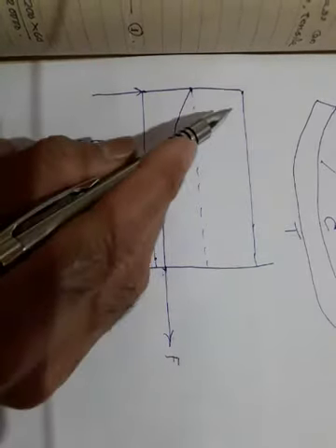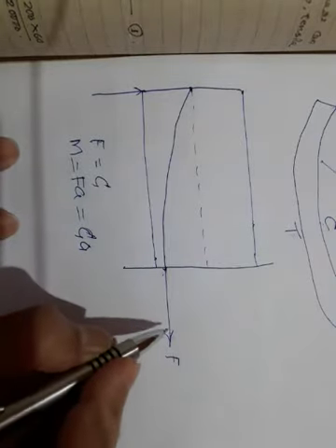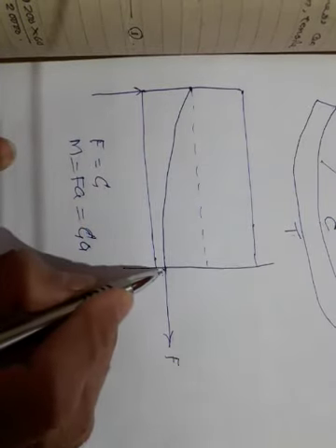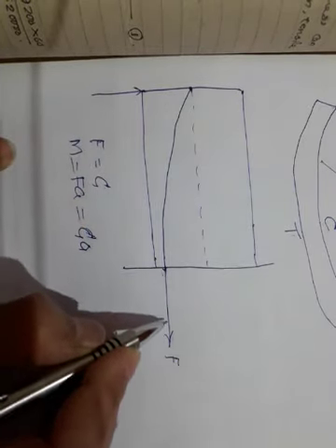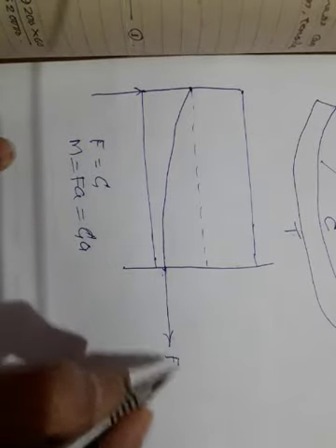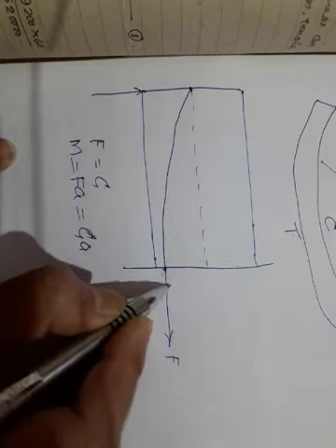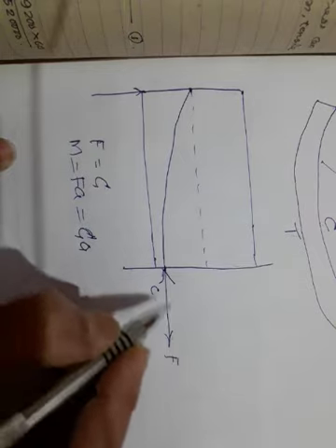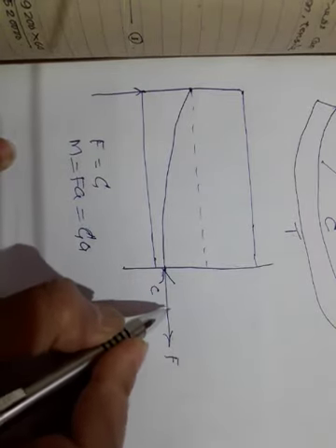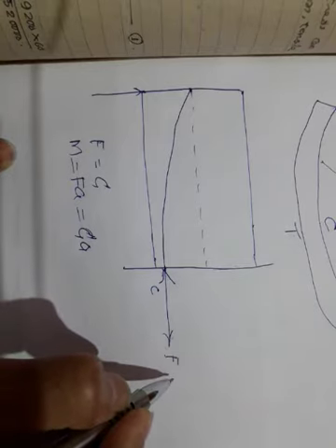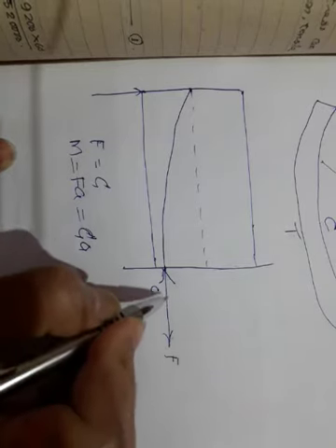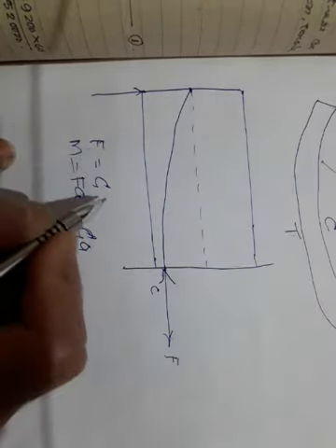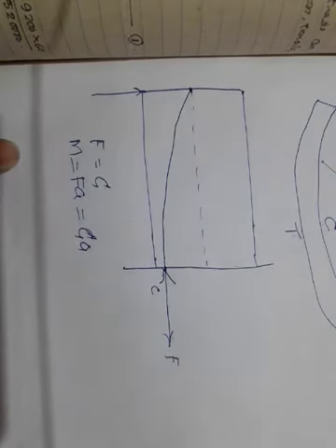Also we have seen that F force and C force are equal. Am I right? F force is the pre-stressing tensile force in steel, and whenever I anchor it, the C force will act exactly here. This is your C force. So with whatever 1000 kilonewton I apply tension into the steel cable, with the same force it will apply the compressive force in the concrete. So F will be exactly equal to C. This is what we have seen in the earlier discussions also.